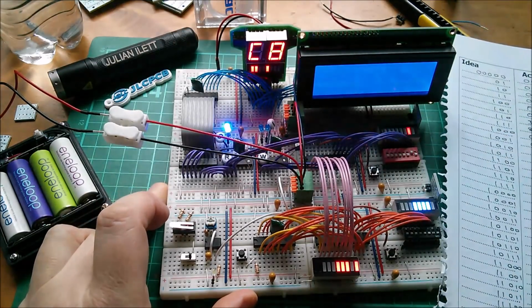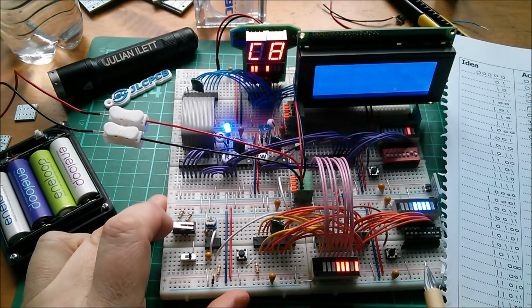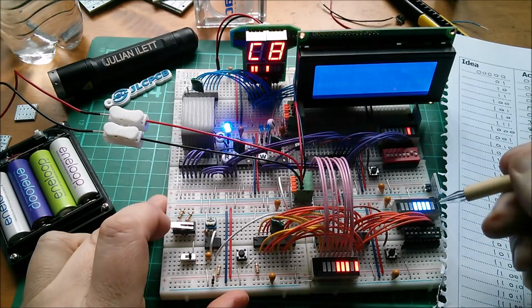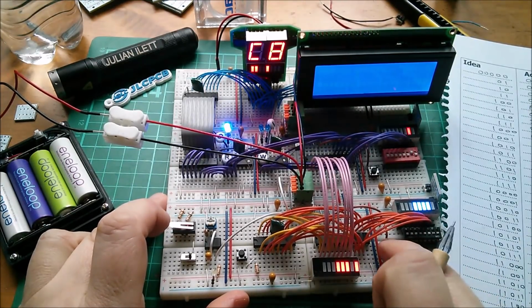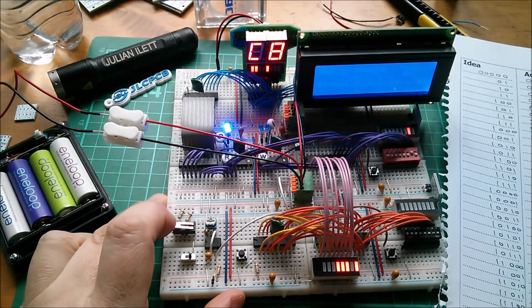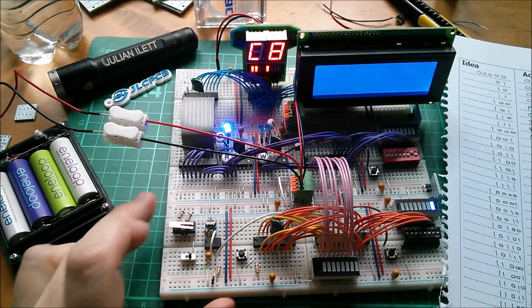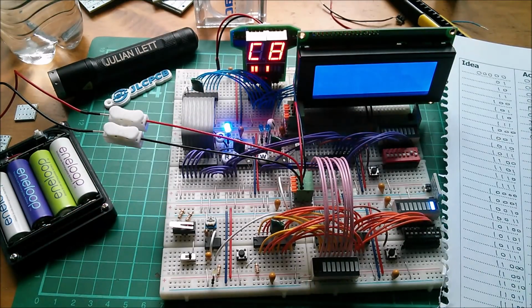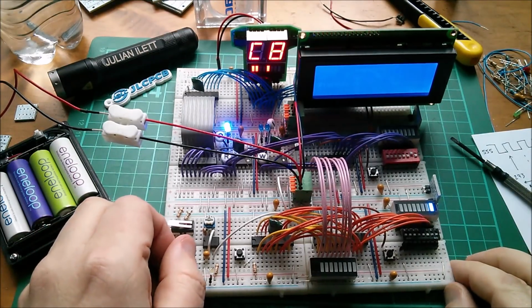02. Now I need to loop back, so this instruction now needs to jump back to address 0. Address 0 is in there, so I program that in. That will do the jump back to 0, and that should be it. I'll leave the camera running because this is the exciting bit. Let's see if it works. Let's free run it.